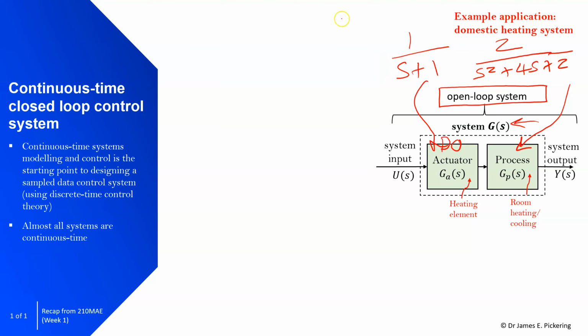So we normally start off with an ordinary differential equation. We then undertake the Laplace transformation. If you remember this Laplace symbol, we normally undertake the Laplace transformation on the f of t, whatever the function is it's looking at. It could be the ordinary differential equation, and then we result in a transfer function. And like I say, we move to the Laplace domain because it has benefits that we can put into the transfer function.